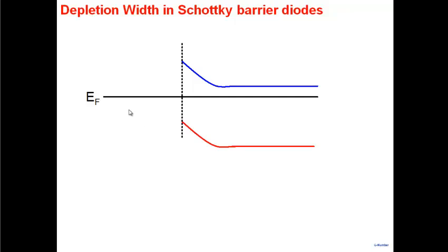And we said that if you take silicon, for example, and take any metal, aluminum, gold, silver, what you end up getting is a barrier height. You find that there is a barrier height between the metal and the semiconductor. And we saw an energy band diagram of the kind that you see over here. By now we are familiar. This is the conduction band, this is the valence band, and this is the Fermi energy here.